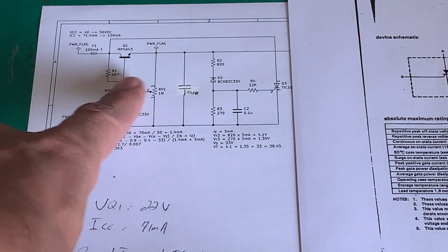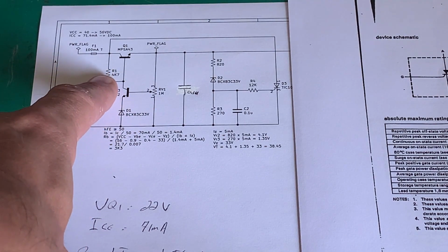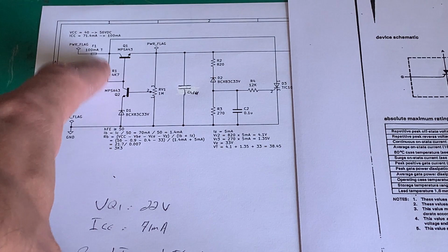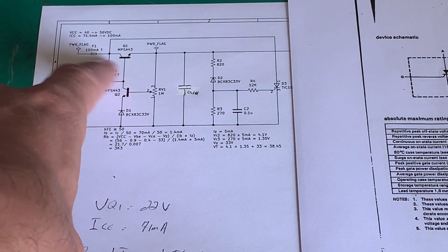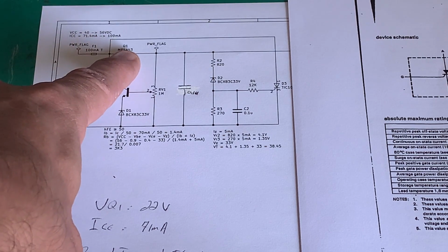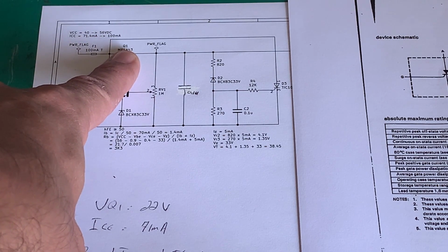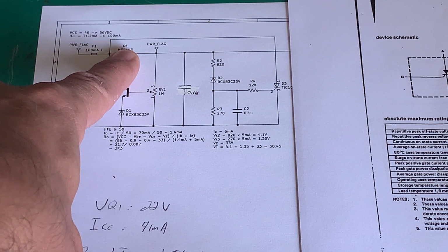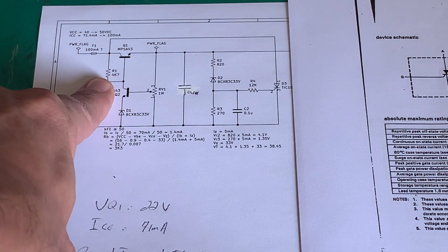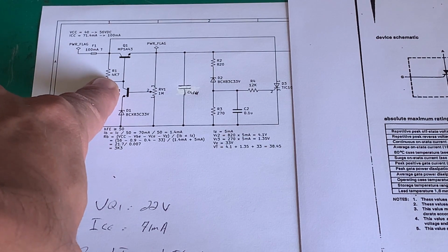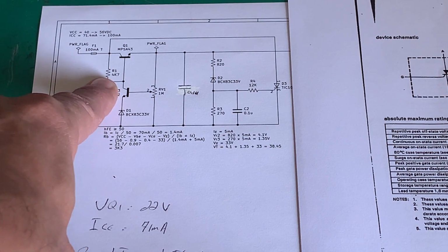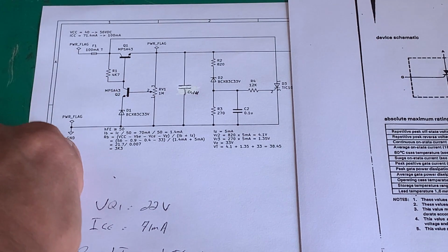But like I've said in the previous video, know that this thing dissipates a lot of power. I mean, we've already seen at full amperage here, we're throwing away 1.5 watts of heat. I mean, that resistor there, if you took the 5 milliamps at the 4K7, you're looking at about 100 and something milliwatts that you're throwing away there, and so on and so forth.